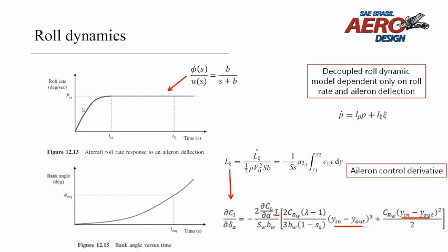The roll dynamic model can be determined as well as for pitch motion, and the algorithm of solution may be the same, as the control derivative contains all the information about the aileron's dimensions. Yet it is slightly different because the control derivative itself is dependent not only on the effectiveness parameter but also on the wing geometry and the aileron span. For this work, the control derivative was calculated for